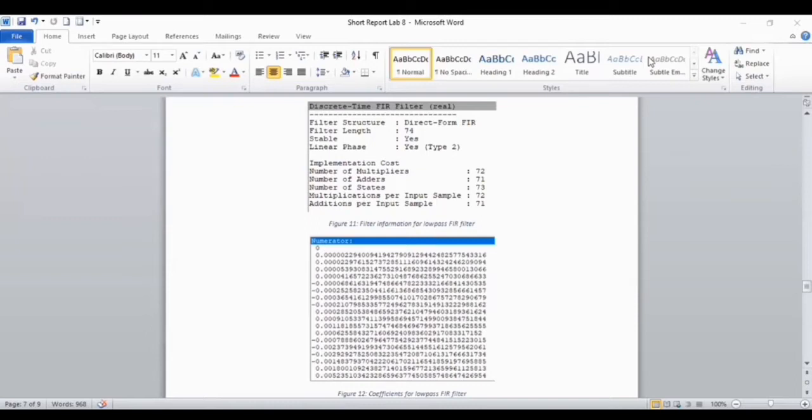As a result, we can get the stable low-pass FIR filter and get 72 multiplications per input sample. Besides, we can get the filter coefficients for the Blackman window technique. The result obtained using the FIR filter is very complex as the order of the filter required is high. Also, FIR filters have constant group delay while IIR filters do not usually have a constant group delay.